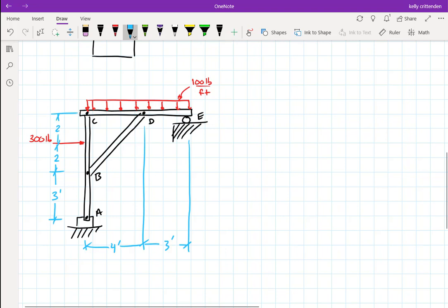All right, so I think that's all that we need for making this into some kind of frame that we can calculate things with. A lot of times it's good to look for 2-force members. This one does have a 2-force member, member BD. So we can somehow mark that. I don't know, we'll color it green. And then usually the first thing you want to do is you want to go in and